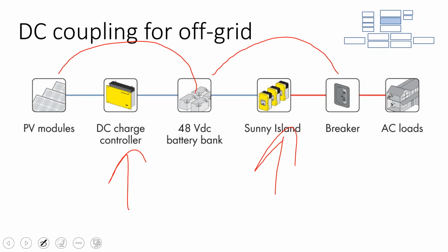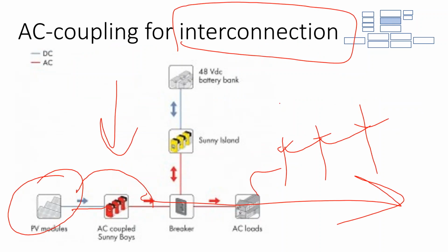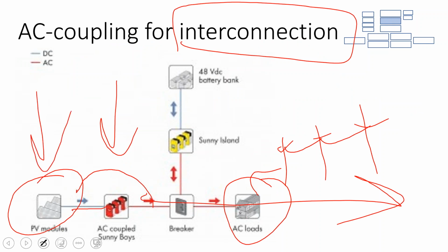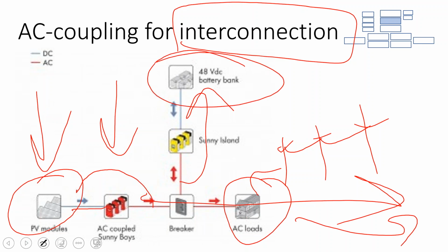And so if your goal is to primarily run off of a grid connection, and you're trying to offset your electric bill with your solar array, any outflow could be used to charge your batteries, but in most cases, a grid-connected battery is going to be just hanging out at full state of charge anyway, especially at the residential level. It's just going to be waiting around for a power outage.